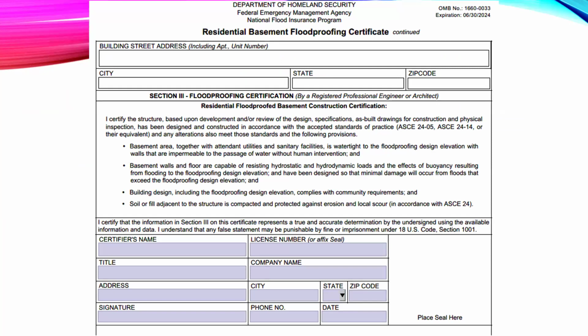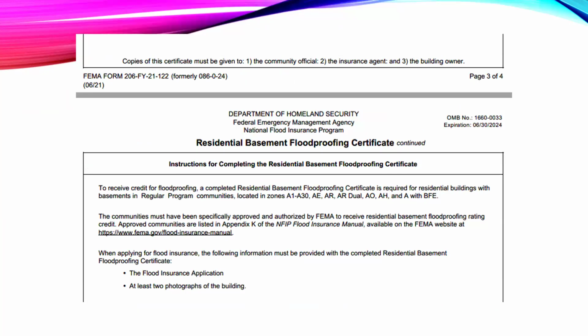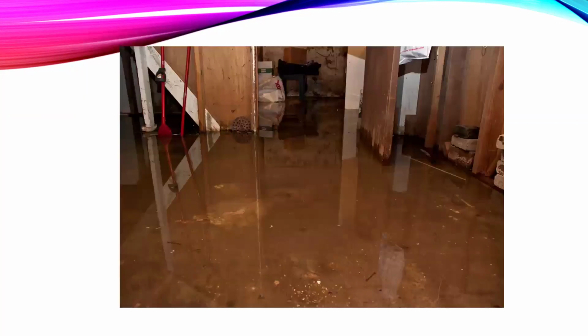Not likely to come across this as a situation. But it is important, I guess, if it comes up, especially when people get confused about the different forms, and then may inadvertently build something out of compliance. Also with this, flooding is common. Again, dry floodproofing has a high rate of failures. So, and then it's not really worth it if people are kind of building a sunken living room. It's just putting a lot of risk to that building for not much payoff.